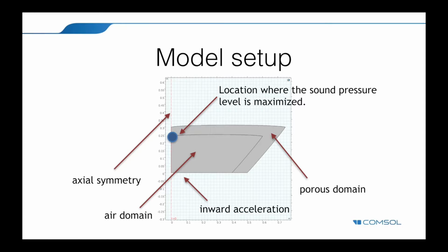The best solution is the solution which, as best as possible, satisfies a list of requirements. For a loudspeaker, examples of such requirements could be maximizing the pressure at a certain point in space or across a range of frequencies, minimizing the supplied electrical power, or fixing the sound pressure level at a specified value. There is in general no unique way of defining the best solution. The concept of best depends on both the application and the appropriate design variables.